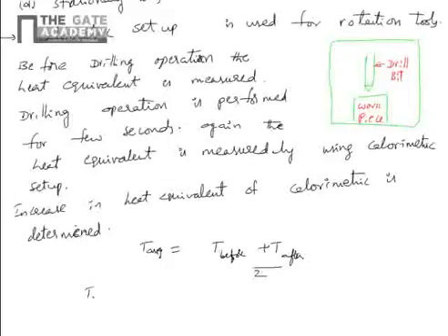Then T max, the maximum temperature at the tip, or T2 in our old notation, equals T average divided by some number, which for a particular tool is 0.4 to 0.5, based on past experiments.